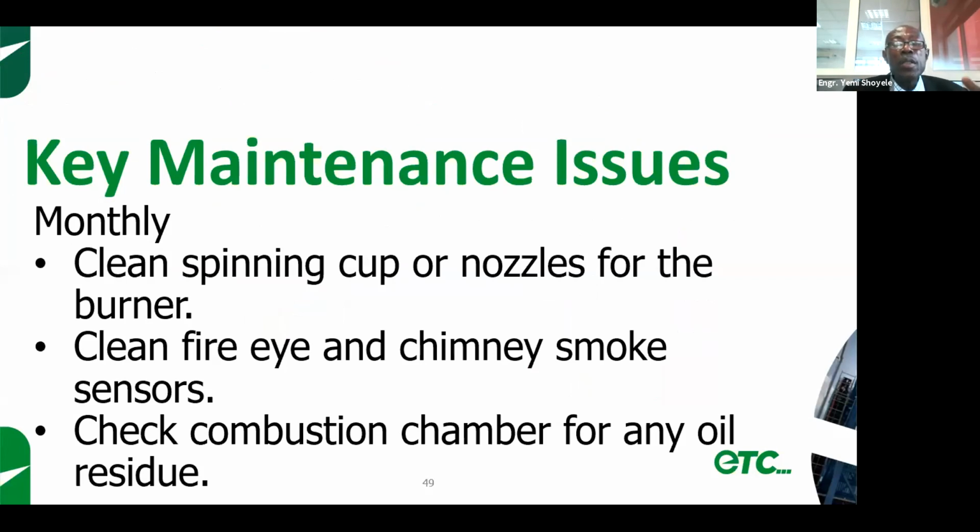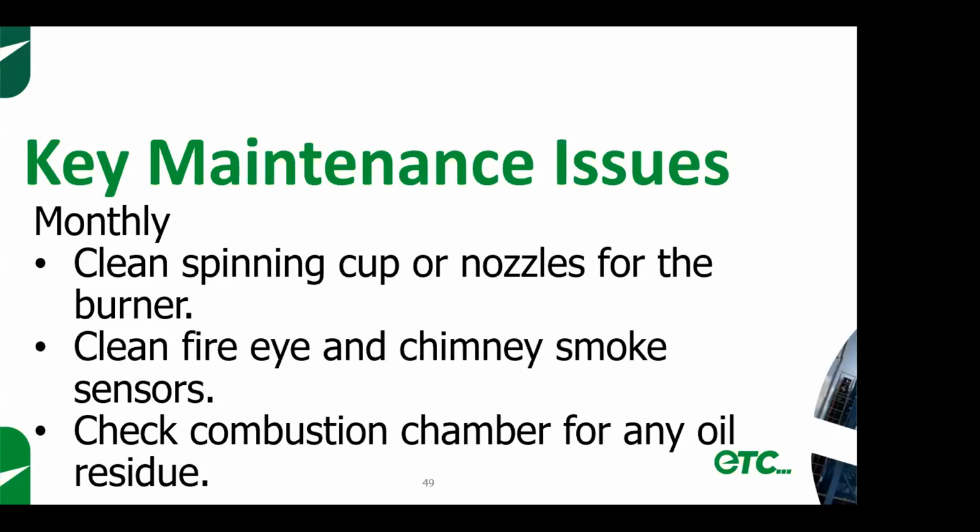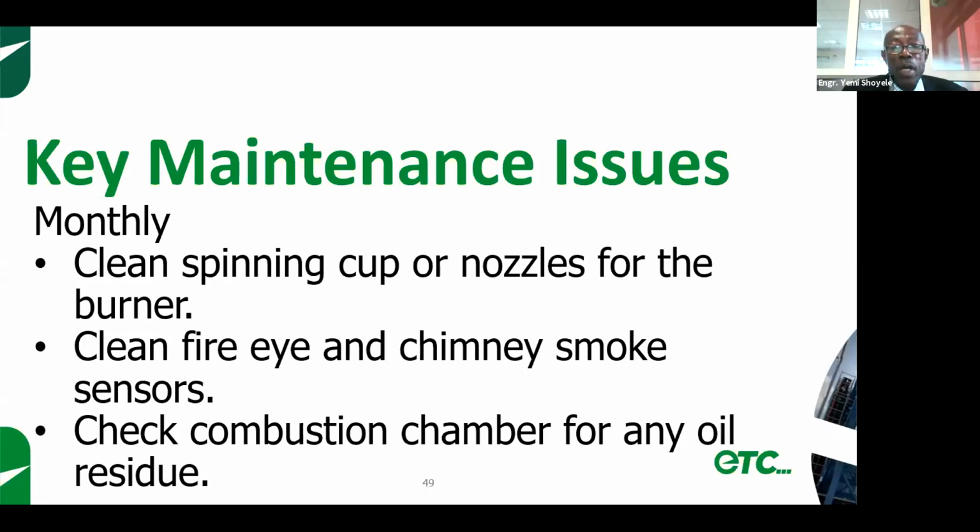You need to clean the nozzles for the atomizer, especially when you're using oil. And the nozzles and spinning cup, if you have a rotary cup type of burner, regularly. Your fire eye sensor and the chimney smoke sensors need to be cleaned. Your combustion chamber needs to be checked at least monthly for any oil residue.